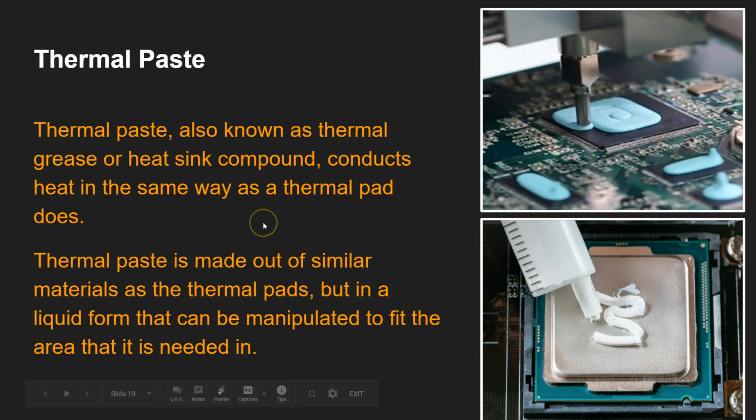Now with the thermal paste, the big advantage is its ability to easily spread. It will conform to uneven surfaces very well and fill large gaps more evenly than thermal pads. This is what makes thermal paste more universal when working with unusual shapes or different configurations of components.